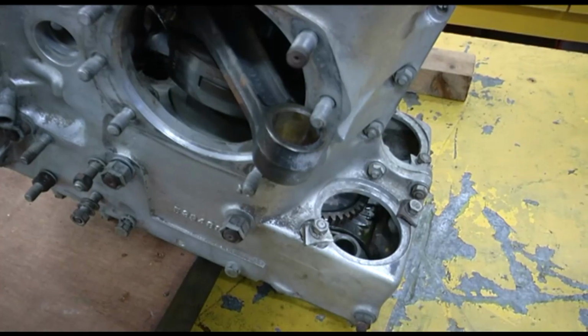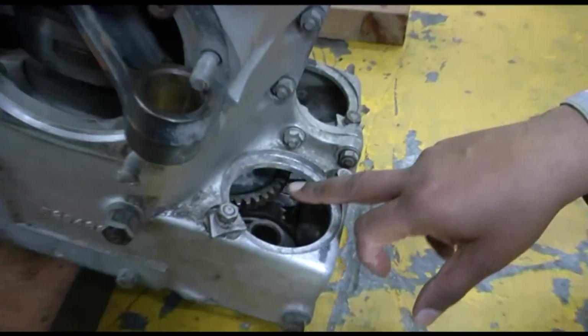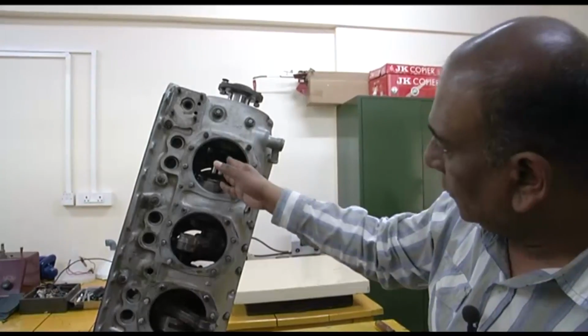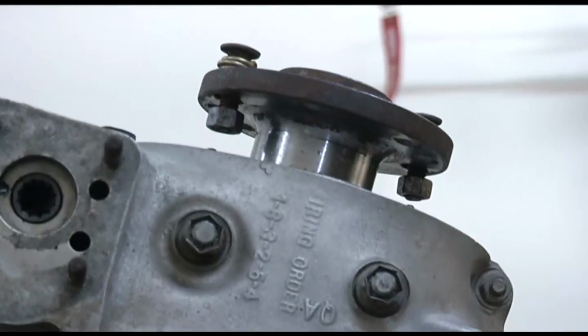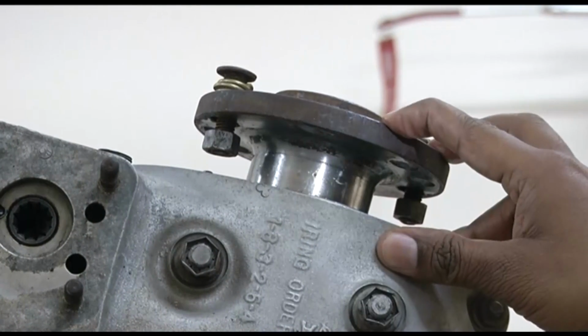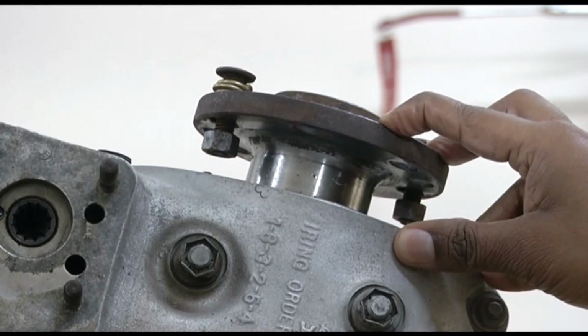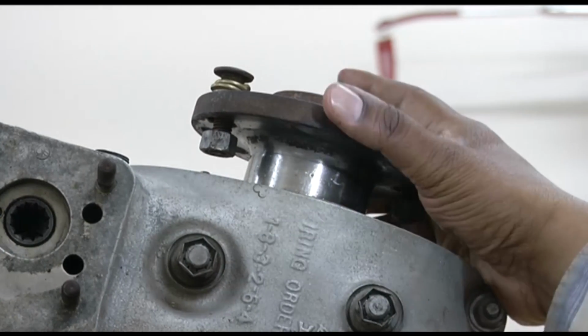We have also seen in the class that the size of the camshaft gear is double the size of the crankshaft gear. So just forward of the crankshaft you have the propeller shaft. Here where the propeller is mounted, this is a propeller shaft. In the class we have seen the different types of propeller shafts, the spline type, the tapered type and the flange type. In this particular engine the shaft is of the flange type.